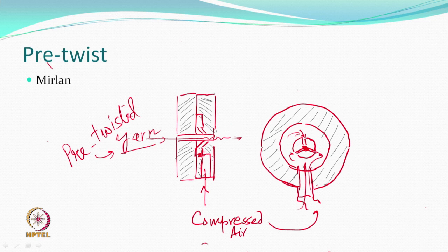So, the air is going to be pushed out generally, but because it is entering the innermost chamber in three directions, it would push the yarn in a manner that it starts rotating. So, a bit of a twist or untwist; we are interested in untwist.